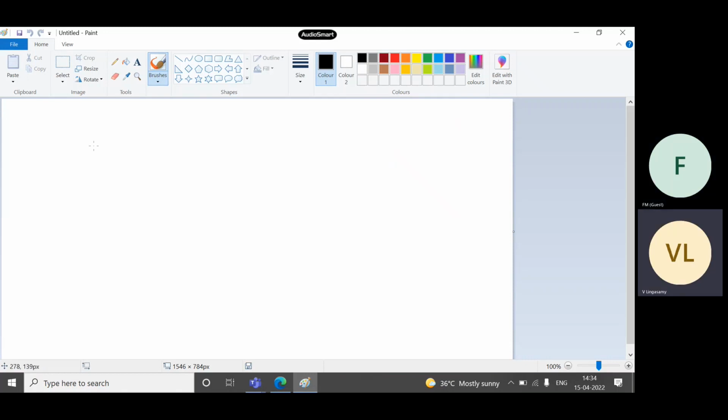Okay. So now see the thing is, there are two kinds of antennas, right? So high gain antennas. Okay, these are all high gain antennas. How do we achieve high gain? For example, if you have a single patch antenna like this, a single patch antenna can give a gain of about 5 to 6 dBi. Okay, but if you want long distance communication, 5 to 6 dBi gain